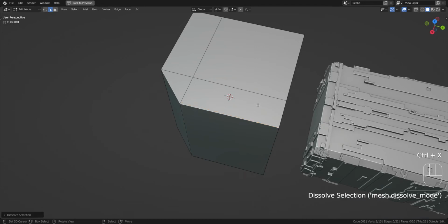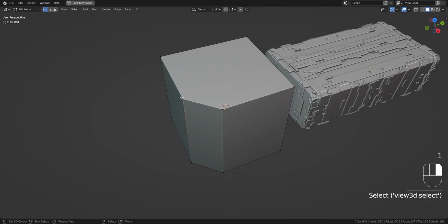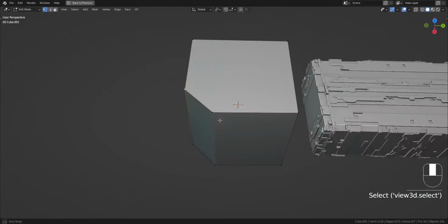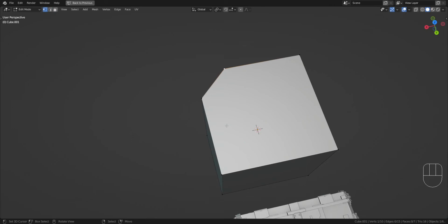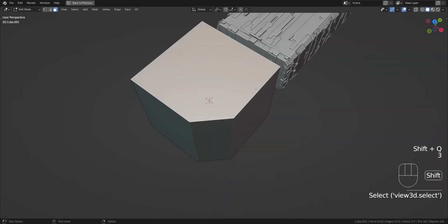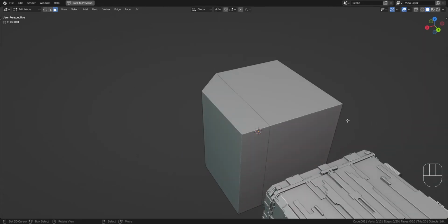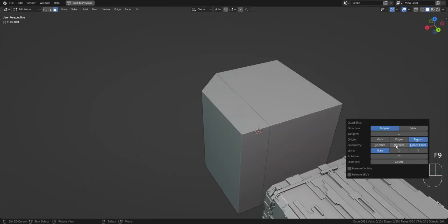So in order for us to just limit the cut to a few verts, let's just select this. We only needed this one to quadify this face anyway. So tag this vert and then quad slice, use the tagged, and then linked faces if you want to cut the island, or all faces if you want to cut the entire mesh.